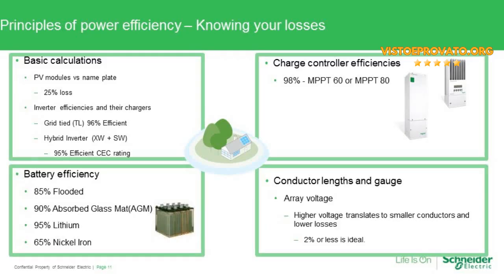I've mentioned my personal system: I've got a 10 kW array, and typically I'll see 7.2 to 7.8 kW, even on a nice summer's day where it's maybe 80 degrees Fahrenheit outside. You just don't get what you expect if you take the nameplate rating, which is really those standard test conditions where the panels are kept cool and the lighting is perfect.